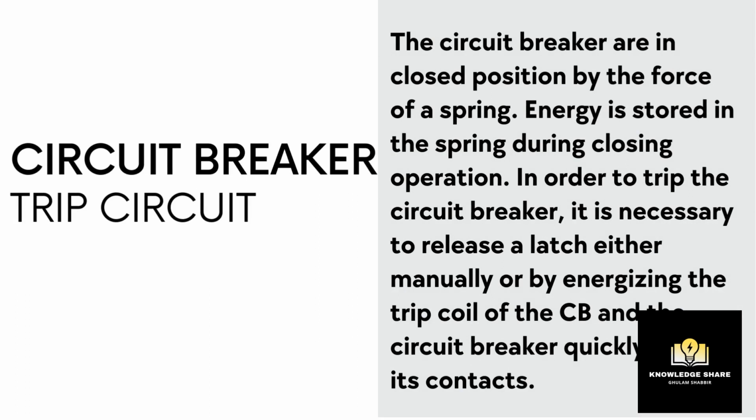The circuit breakers are held in closed position by the force of a spring. Energy is stored in the spring during a closing operation. In order to trip the circuit breaker, it is necessary to release the latch, either manually or by energizing the trip coil of the circuit breaker. And the circuit breaker quickly parts its contacts.